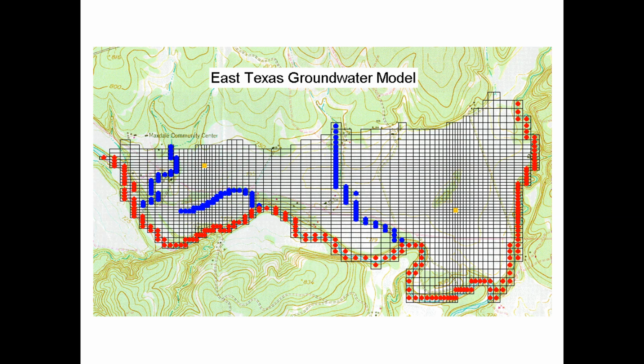And then these little colored dots represent the actual application of boundary conditions to those cells. And then we run it through a solver, and it ensures that at each of these cells, if you look at the head at each cell in relation to the other cells around it, that governing equation is satisfied.